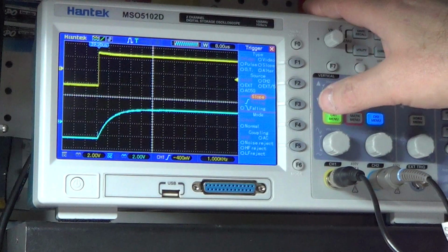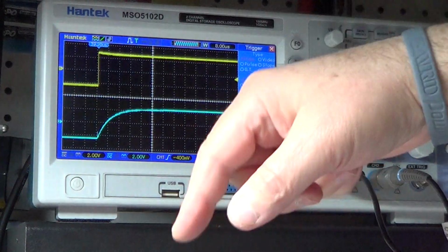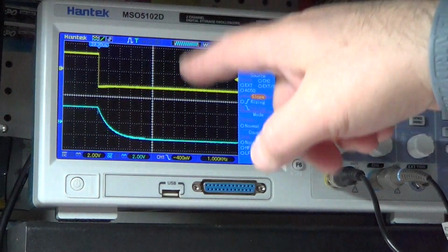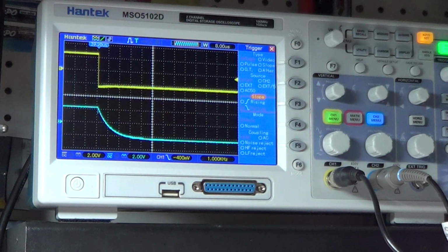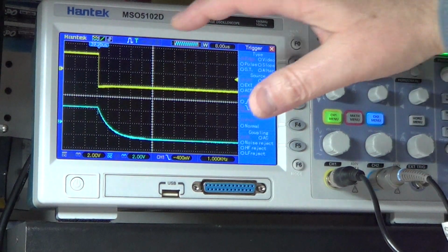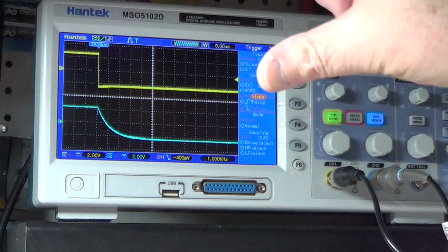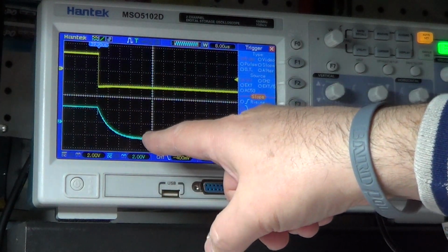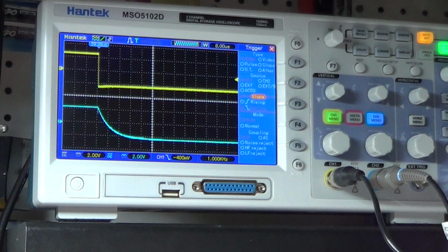So now let's go to the other case where we remove the voltage suddenly, which is this one. This time the magnetic field is there on the inductor and needs to go away, so it provides a back EMF that sustains the current when the voltage goes to zero and dissipates the energy that was stored in the magnetic field a little bit at a time. So the energy goes away, and while it goes away the back EMF reduces, and consequently also the current becomes smaller and smaller until it goes to zero when there is no more magnetic field stored in the inductor.